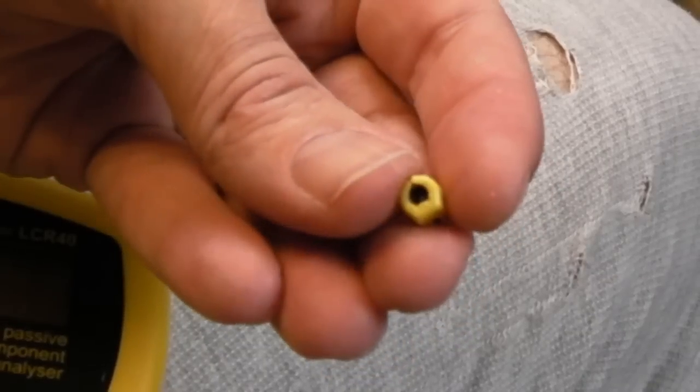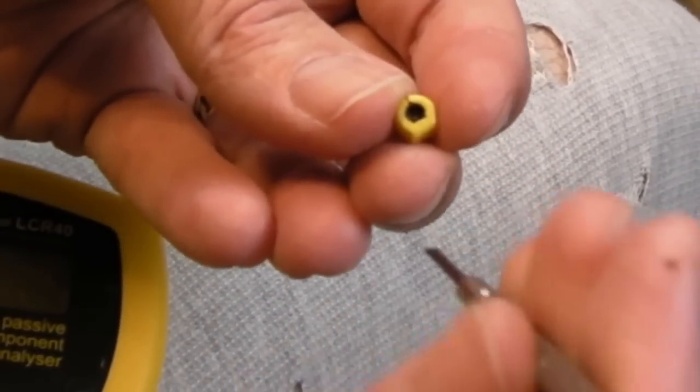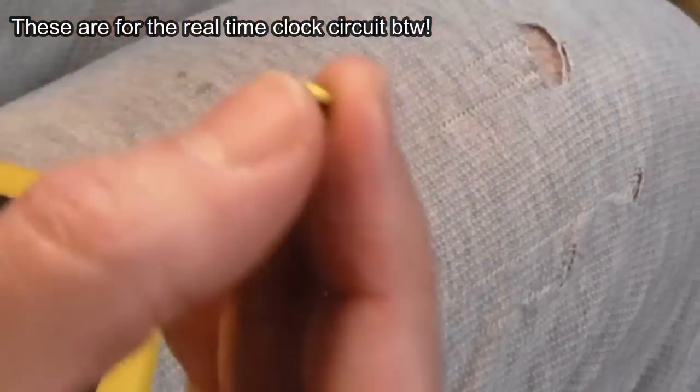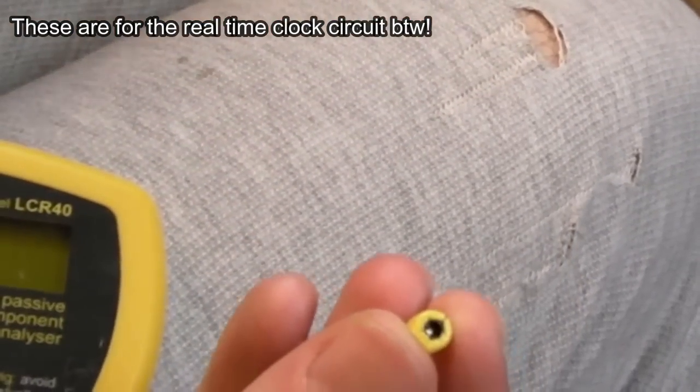I will clean it a few more times, and obviously we'll calibrate using the scope there just to see the effect that has on the 32.768 kHz signal. But anyway, right now I'm going to get that on a brand new crystal and the original 100k resistor.